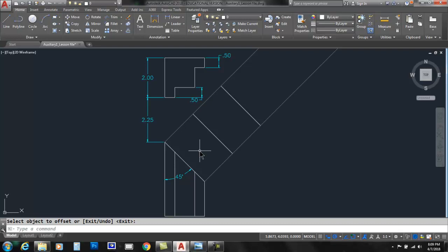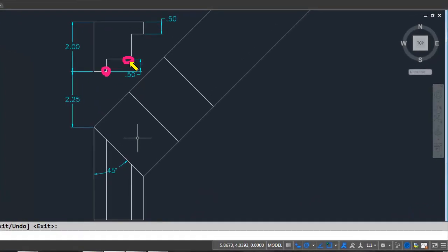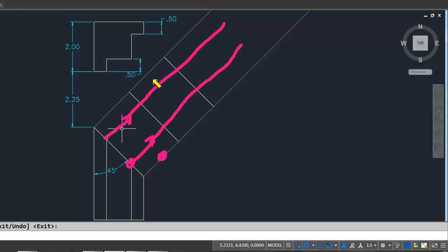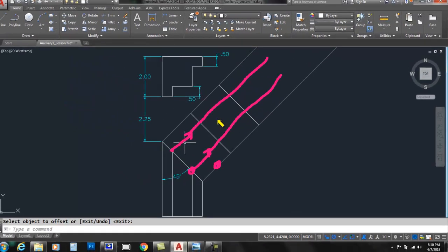Alright, so one way of understanding this is to know that for every one of these edges here, here, and of course the 2 outer edges, if we project straight down, it'll line up with these lines here. Just like the outer edge would come down and then go 90 degrees in that direction. So we don't need to project down because we know they arrive there. However, they will go 90 degrees in this direction. So what I'm going to do is simply copy one of these at these 2 points here, so that I will have 2 more construction lines. And I'm almost creating a grid or matrix like chart in there.